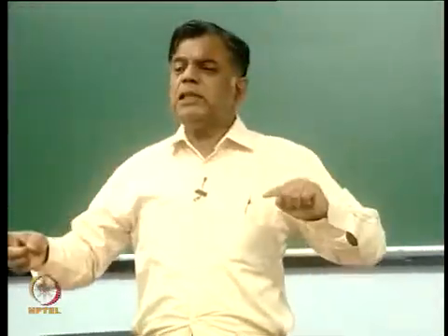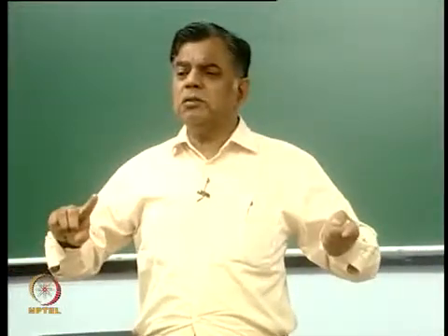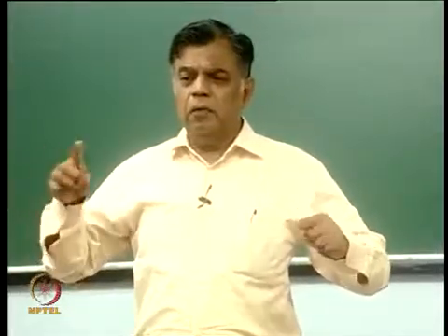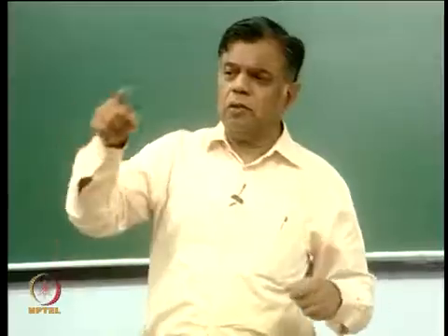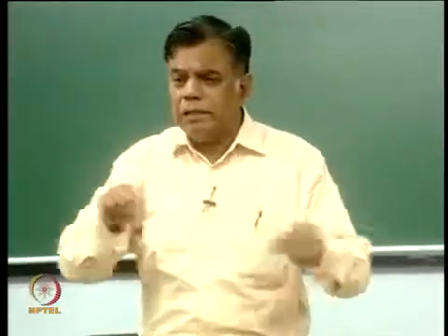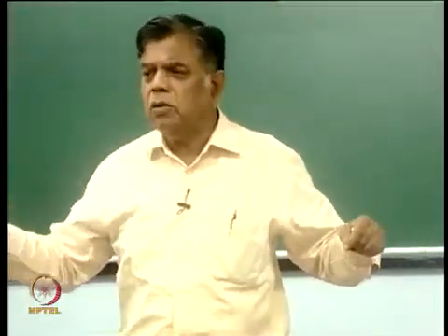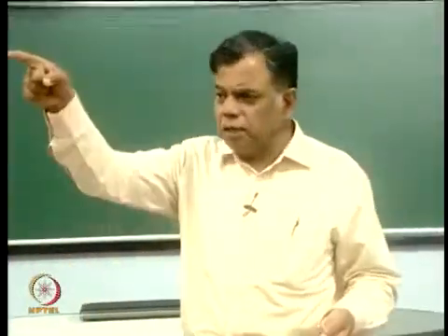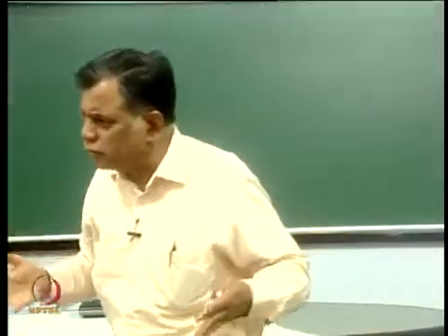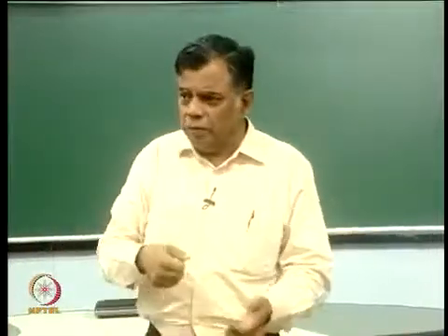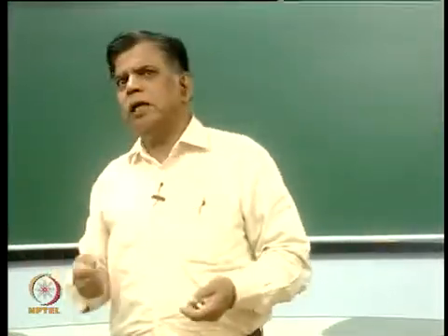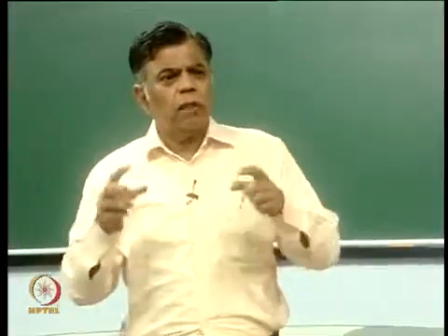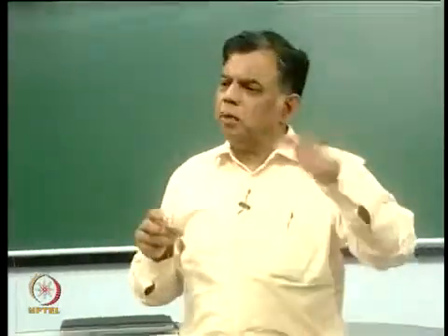You cannot simply say energy equation. Energy equation is not enough by itself. For you to solve the energy equation, you also have to solve the flow. What is there in the energy equation which makes you so? Here you have u. That is the difference between your conduction equation, which is the energy equation, and this equation. Fluid flow affects your energy equation. So u dT/dx, v dT/dy. For you to get this, you have to solve the momentum equations.